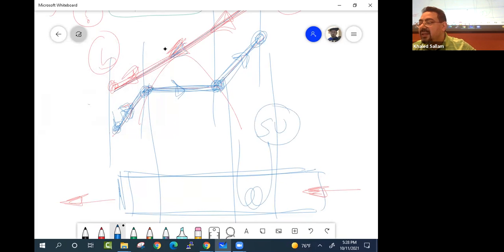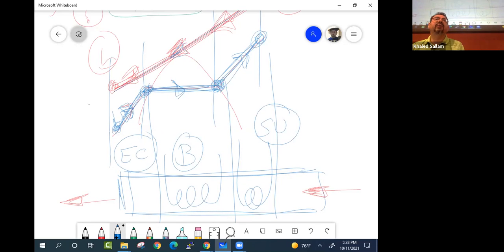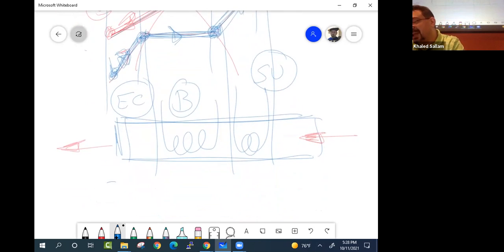And then this is the boiler pipes. And then this part, the last part, which now the hot gases are the coolest because they went through a lot of cooling, and the water is the coolest. This part is called the economizer. Economizer, like it's very economical to use it. Why? Economizer.